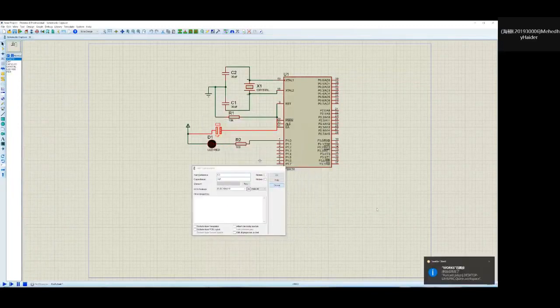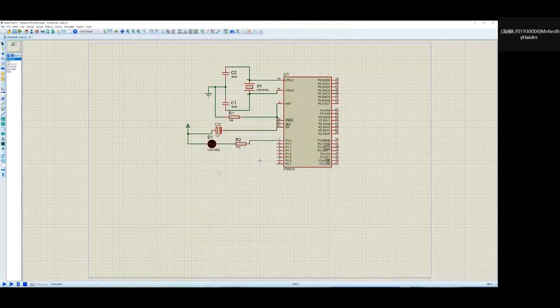So what is the name of the component you connected to C3, the pointy one, like the arrow? The arrow with C3. The arrow? You mean this component? Yes, sir. It's power, the VCC. VCC, you can select it from the same place as ground. Click the terminal mode, and you can find the power and ground. Power is what you see as the arrow.